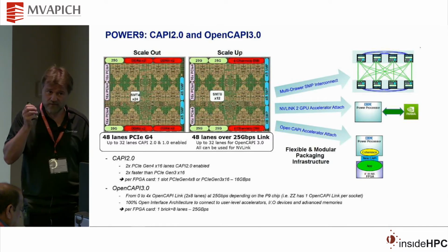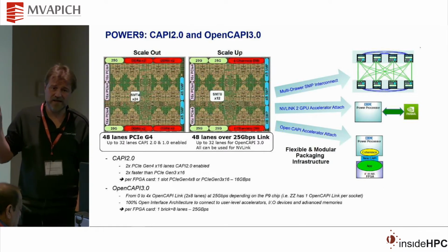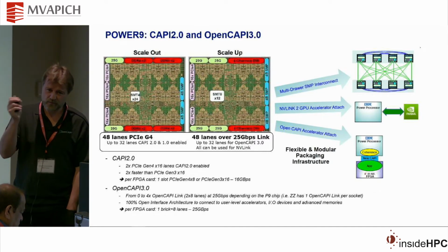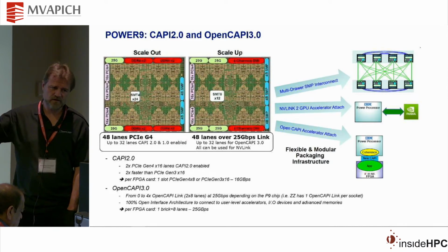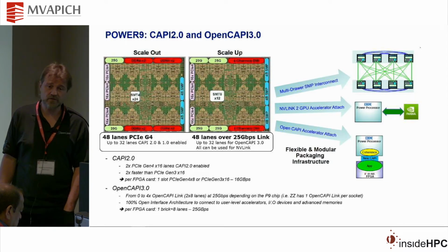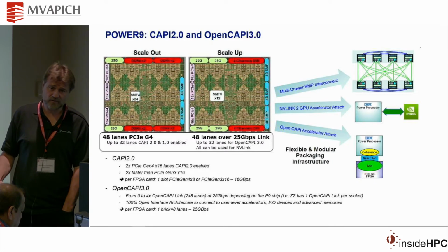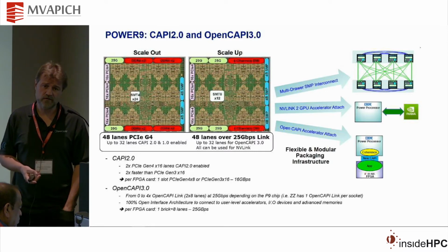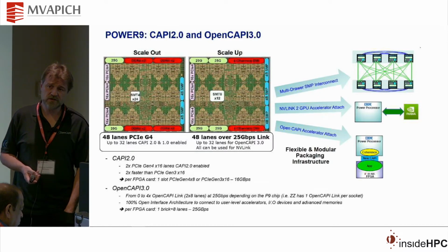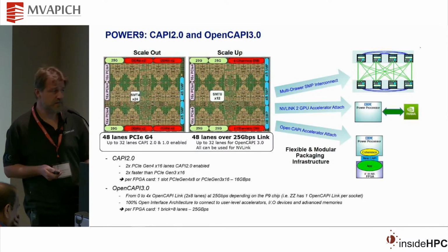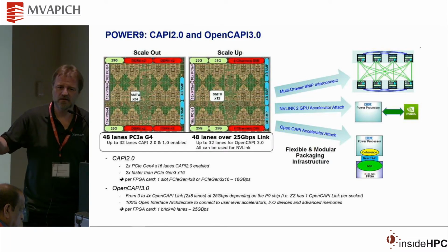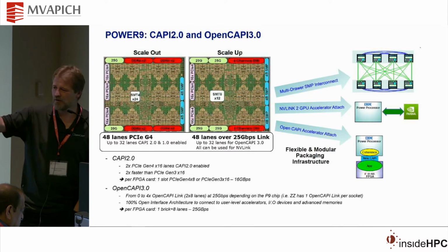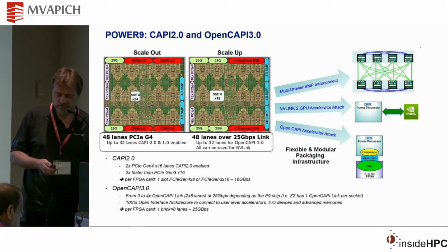The same fast link can be used for NVLink or OpenCAPI, but the protocol is a little bit different. So when the OpenPower manufacturer builds his system, he makes his own choice how he will dedicate the pinout of the component to which connectors he wants. This is how, at the end, you get so many CAPI2 capable ports or OpenCAPI capable ports on your chosen machine.